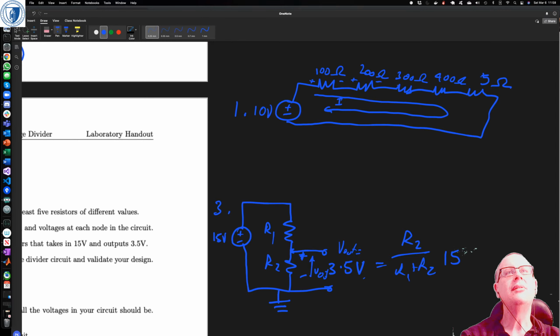And remember, there's a little bit of an issue as far as how you measure the voltages, and in fact how you measure the currents. You would expect all of the currents for R1, R2, R3, R4 and R5 to be the same, but depending on how you added the resistors to the circuit in LTspice, you may get them the negative of each other. And the fix is easy.